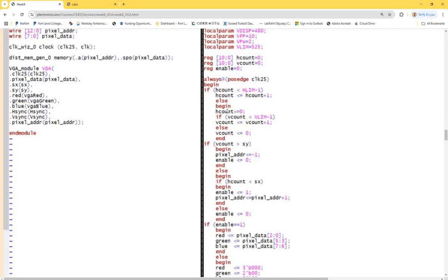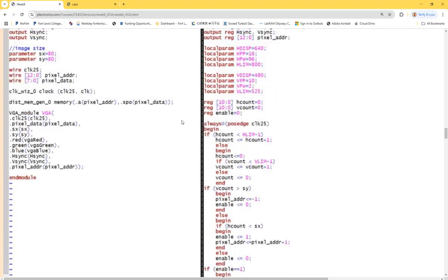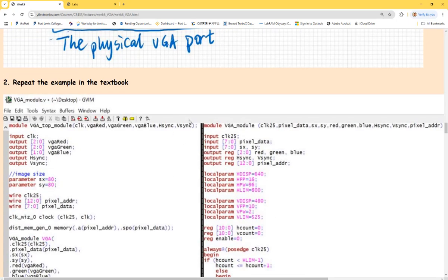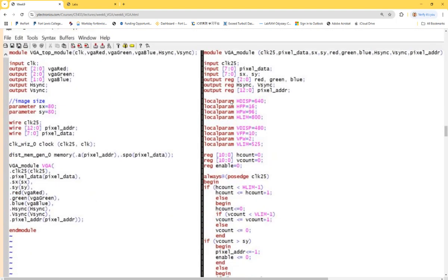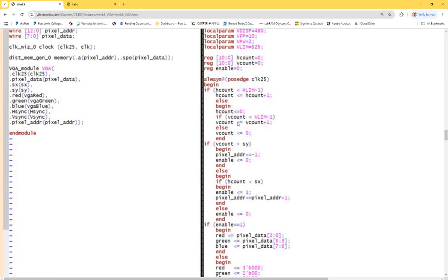So this is given, right? If you plug in and run it to the board, you should immediately get a Basys 3 board picture on the monitor. This should be simple. The way that works is it's just scanning through the horizontal and vertical counts, and seeing if it's reaching the limit.